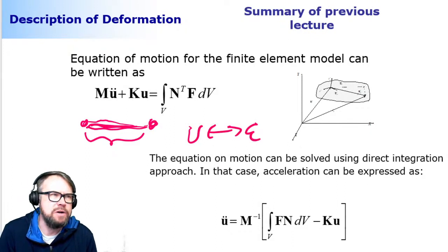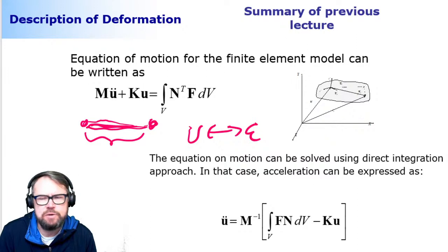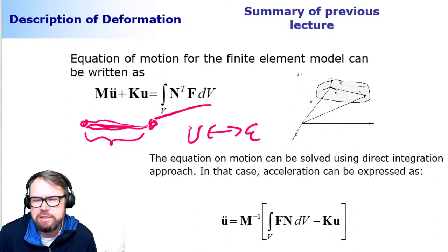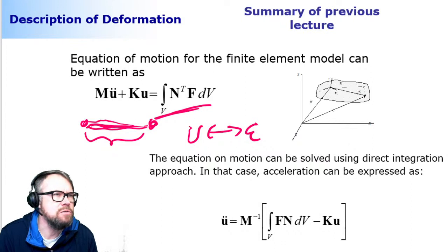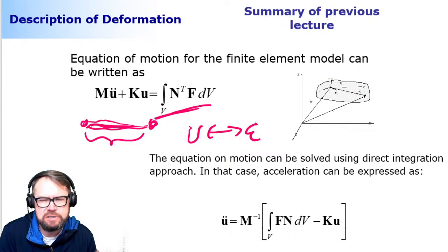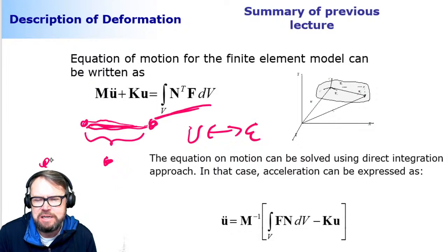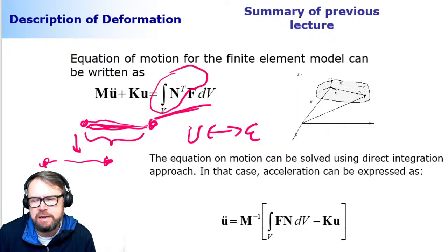And then you can express your stiffness matrix and your mass matrix, which is your inertia description. And even with the help of shape functions, you can express how the distributed load, or to be more specific, the load force that is not in the nodal location, can be expressed in terms of nodal degrees of freedom. And that's the way you can make that happen.